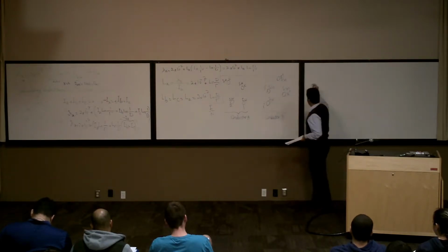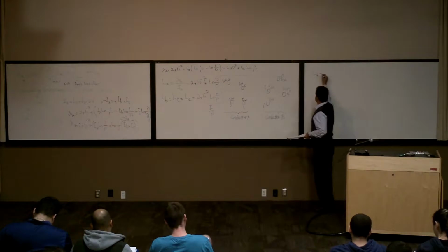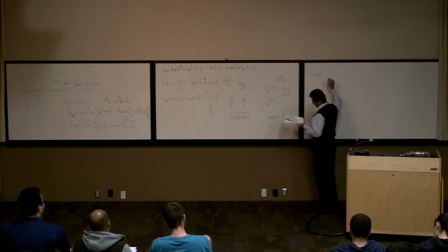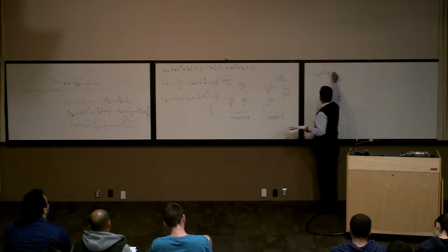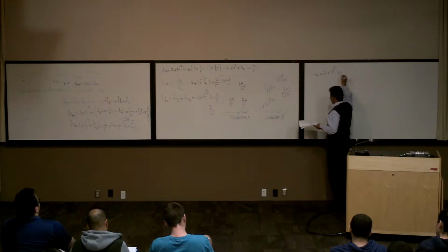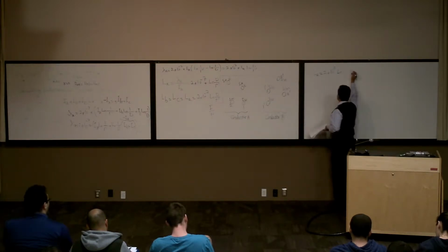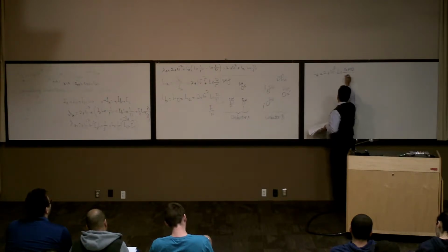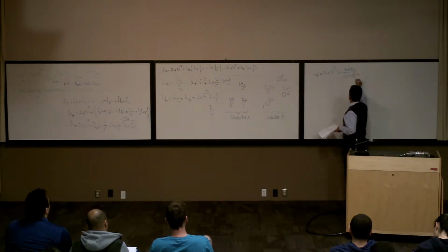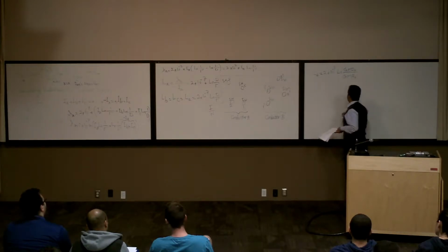So the inductance of conductor LA is going to be 2 times 10 to the power of minus 7 ln of GMD over GMR A, because this is for LA.